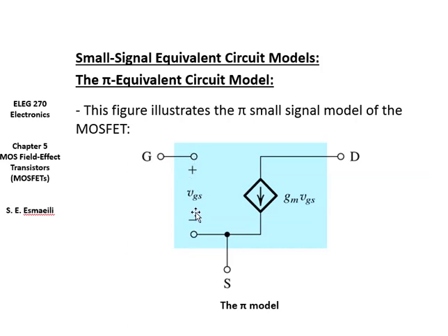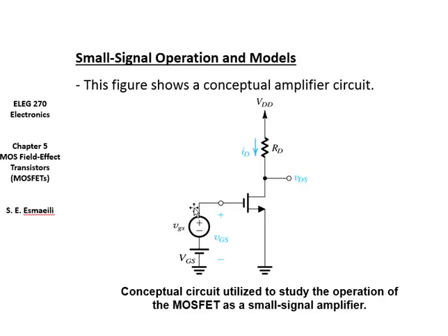Do you know why? Because in MOSFETs, the gate does not draw any current. The current at the gate is 0. So you can tell, look, here if you had even a 1000 kilo ohm of resistor, you wouldn't care because there is no current in the gate. So there will be no voltage drop here. So whatever the voltage is here, we will have it right at the gate. So this makes the analysis of the MOSFET much easier.